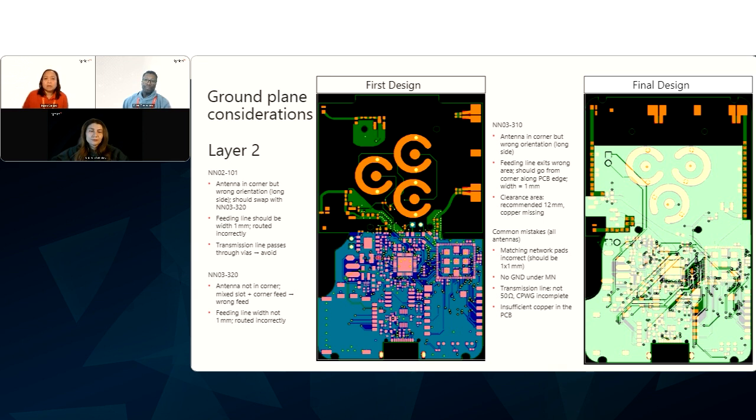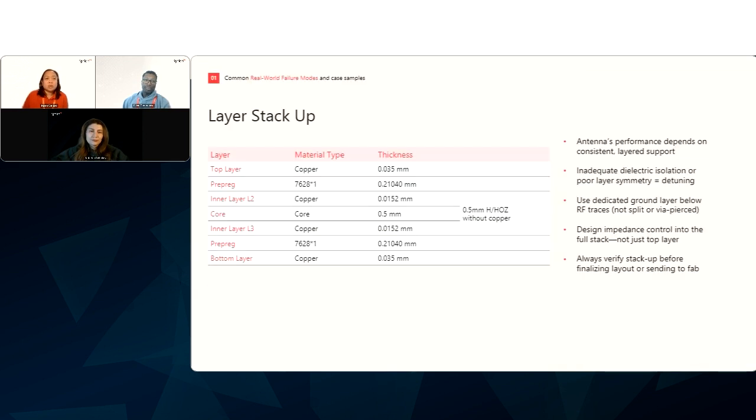And then there's also the layer stack up. Perhaps a couple of tips on this one? Yeah, sure. The layer stack up is important, basically, because your PCB is essentially the carrier for different signals. So the RF layer typically is on the top, and that's where you integrate your RF components and design your transmission line, et cetera.